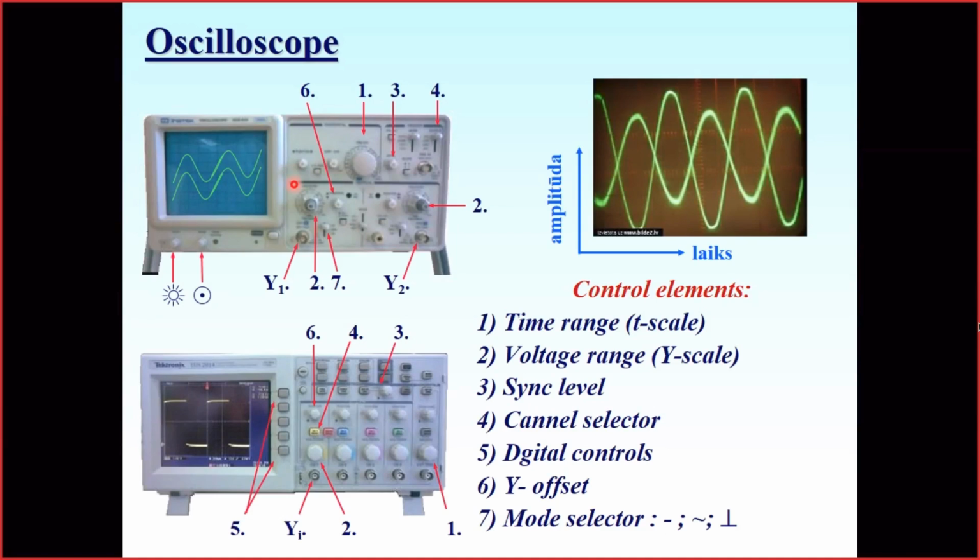When they are not synchronized, the new waveform of this signal will be drawn from another starting point. That's why all these separate drawings overlap and make a wide and bright ribbon on the screen, and we couldn't distinguish a separate waveform on the screen.